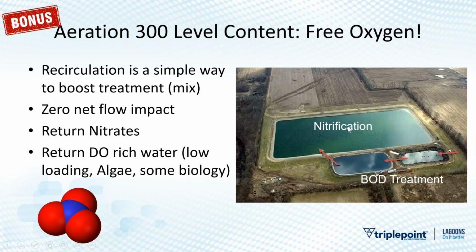And in this application, after nitrification, the ammonia becomes nitrite and then nitrate. Nitrate is a molecule right here. It is a nitrogen molecule in the middle with 3 molecules of oxygen bolted onto the outside. There's lots of oxygen in that nitrate. What you can do is add a flow backwards, do a recirculation of 0.25 up to 1 Q, or 1 times your flow. You can use a trash pump or whatever you want. And you pull the water laden with nitrates into this cell. And because the cell is partial mix, or assuming the cell is partial mix, there are some areas of anaerobic treatment.